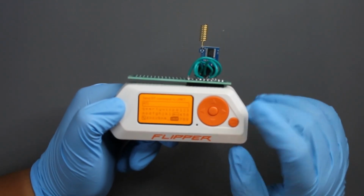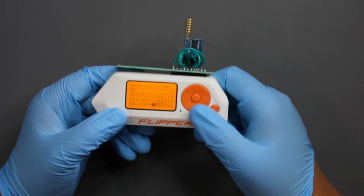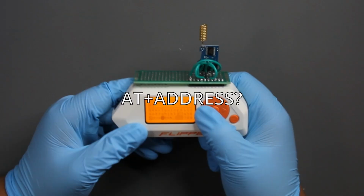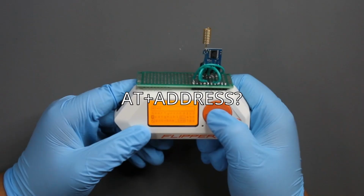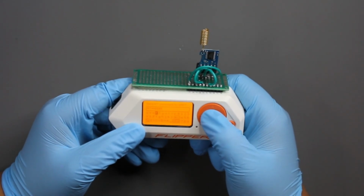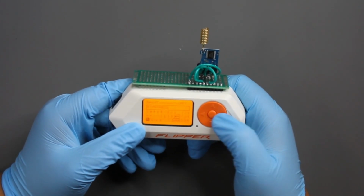So what you're going to want to do is type in this code to show the LoRa address for the LoRa module. To find the address for your LoRa module, you're going to want to type in this. I'm going to put it up on the screen if you can't see it. It's basically AT plus, and in all caps, ADDRESS, and then a question mark.